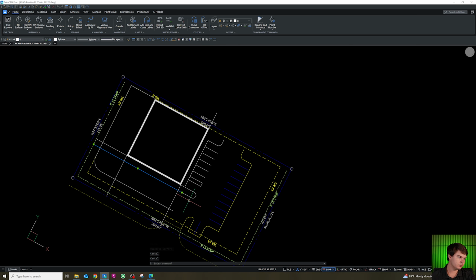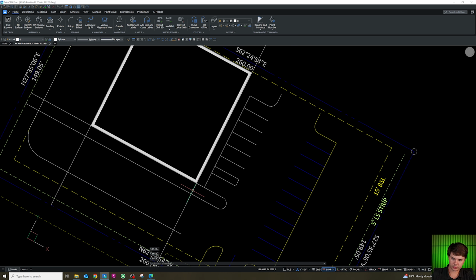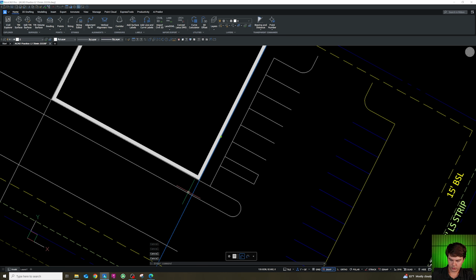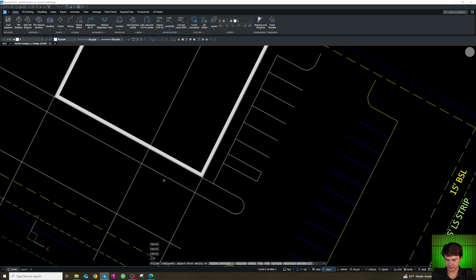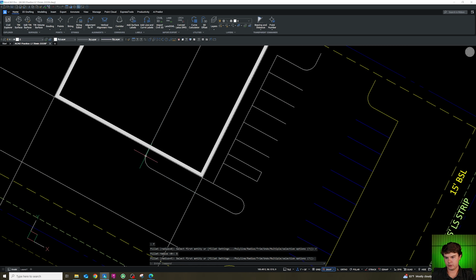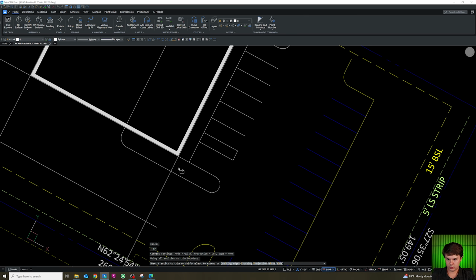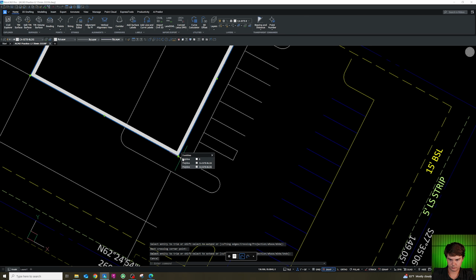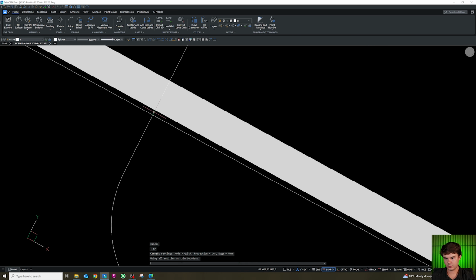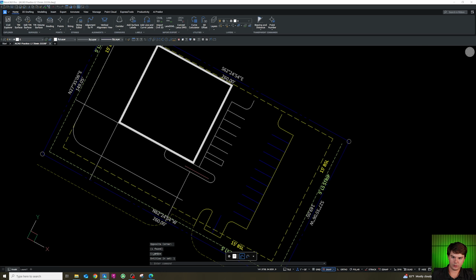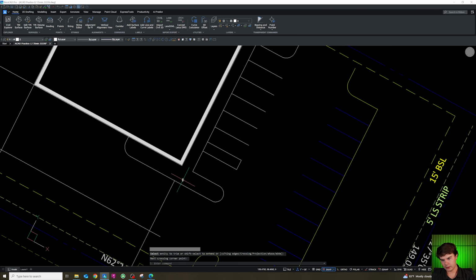It looks like we've got about 30 feet for the entrance, so I'm going to just offset that, looks about right. 30 feet just for the front entrance sidewalk. Give this a fillet of 5 and then trim. Delete. Trim this away as well. Now we've got our island, wraps around.